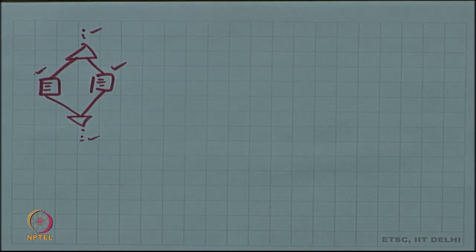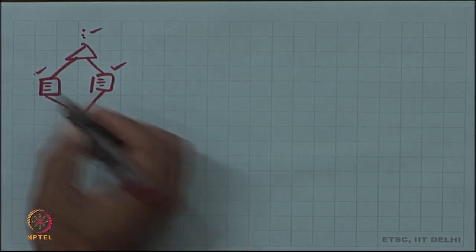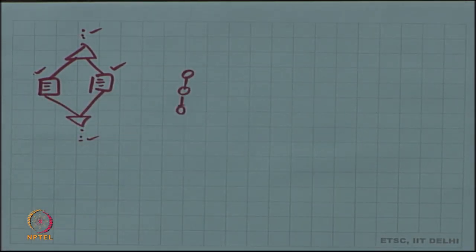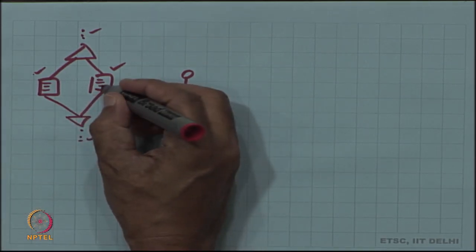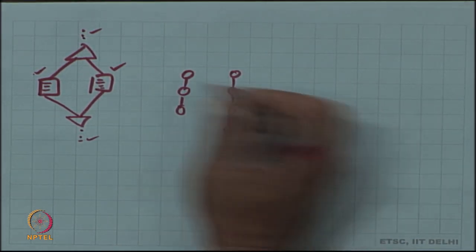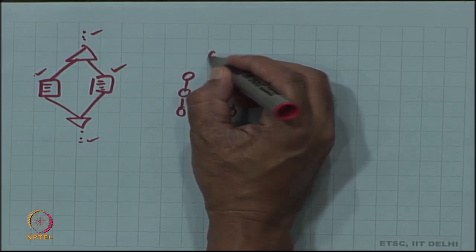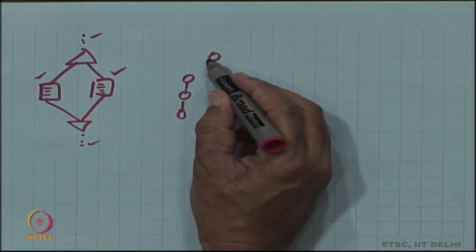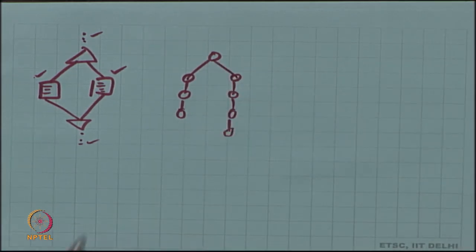Each would lead to a partial finite state machine, right. If this was 3 states, then I would have a sequential FSM with 3 states. If this one was 4 states, then I would have an FSM that looked like that. A condition here, if that condition check is performed in one cycle, would look like that.